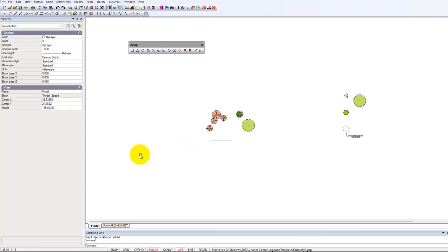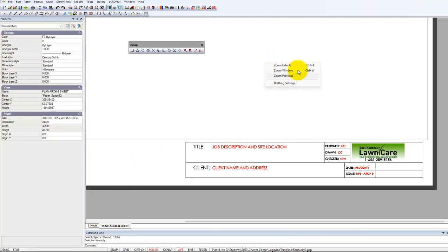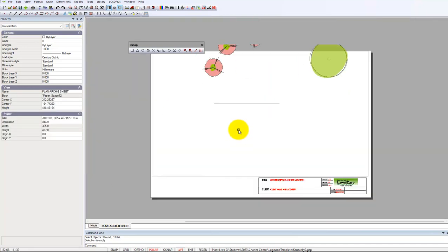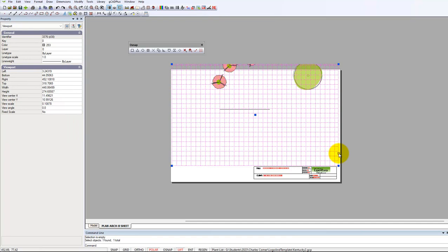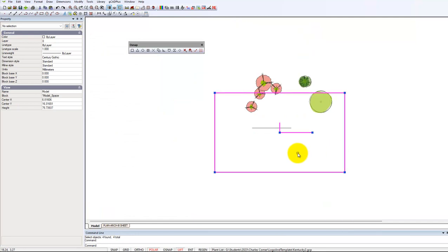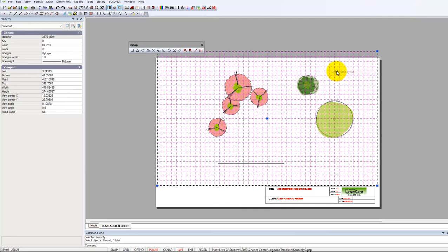When we want to see how the drawing would look, just swing to that architectural C size sheet, and you can see it's not quite positioned correctly, and that's because it sits in what's called a floating viewport, and we want to activate that viewport and just reposition things. Can you see I can move that up like so and display on the layout?